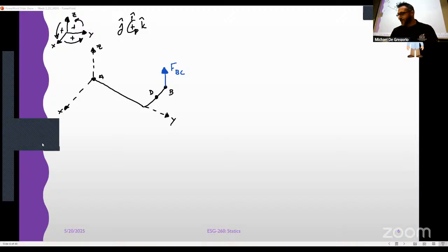So our thrust bearing. We look at the textbook, right? Textbook shows us that we've got 5 reactions on here, right? Okay, we know this is a 3D problem, so the maximum unknowns that we can be looking for is 6. Remember, you have 3 equations for force and 3 for moments. That's 6 equations, 6 unknowns. So if this were fully constrained at A, we would be over-constrained and statically indeterminate, so we can't do our analysis because we'd have more unknowns than we have equations, right?